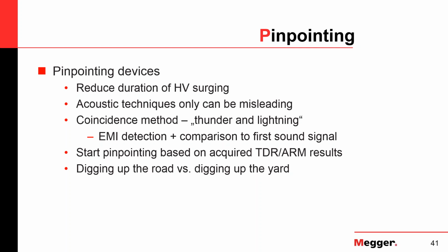So the pinpointing device actually reduces the time that you need to be surging. From your prelocation, you already have an idea, plus minus 1%, where the fault is located. You walk in the proximity of that. You tell your crewman to turn on the thumper. You bring your pinpointing device, and you will find the fault fairly quickly, and there's no need of thumping around for hours.